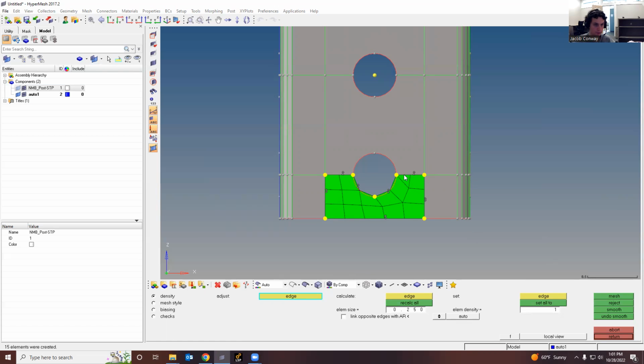So this right here is where meshing becomes sort of a puzzle. You've got to make it look as rectangular as possible by increasing or decreasing the number of nodes on a certain side. So yeah, that's what I'm doing right now. This is going to look very repetitive because, again, I am a novice at this, but let's see. Yeah, this is a bad mesh.